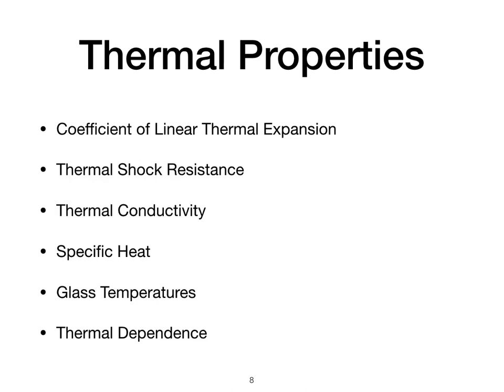Thermal shock resistance. Thermal shock resistance of a glass indicates how likely it is to break when its temperature suddenly changes. It is defined as the maximum change in temperature that a glass can withstand upon rapid heating and cooling. It is related to the internal stress necessary to cause cracking or failure, Poisson's ratio, Young's modulus, and coefficient of linear thermal expansion of the glass.